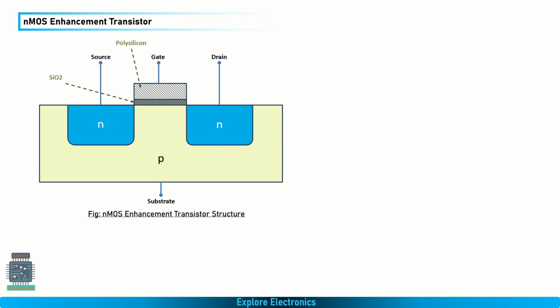So this is enhancement mode transistor, where there will be no connection between the source and drain for the current flow. We need to create the channel between source and drain by applying the extra voltage from the gate. Now, if you look at this further, there will be two back-to-back diodes formed inside because of the N and P regions. This is N region, this is also N region, this is P region.